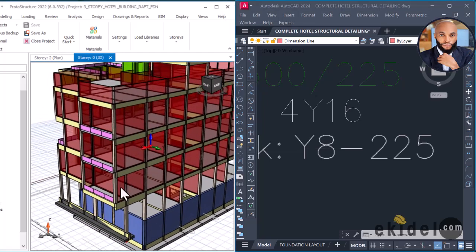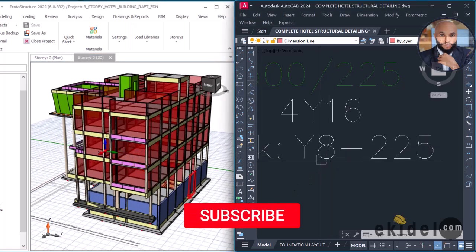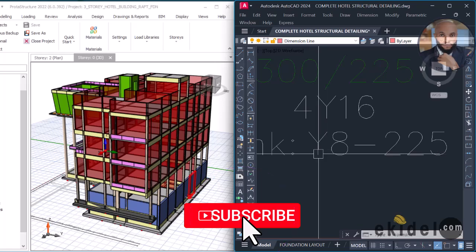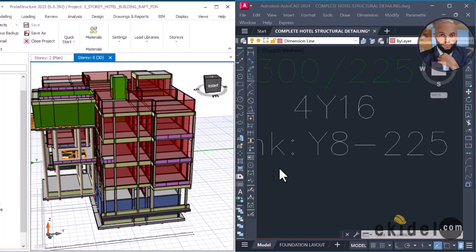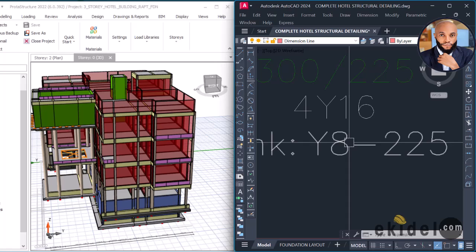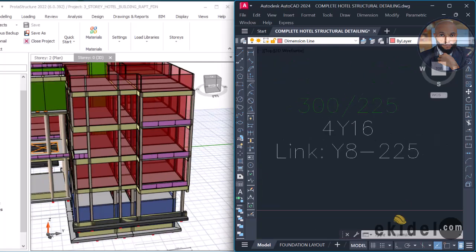Most companies manufacturing this steel are compromised to the extent that when they manufacture diameter 8, it might turn out to be diameter 6. So because of that, I want to avoid the issue of using diameter 8, because when you go and purchase it from the market, you will see that what you are buying is diameter 6 and not diameter 8. And that will affect your design, because you designed for diameter 8, but in reality, if you measure it, it gives you diameter 6, which is very bad.